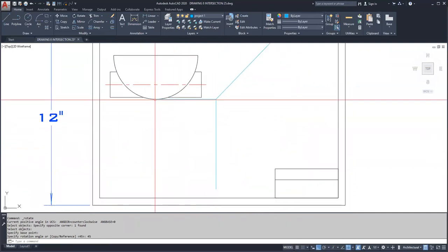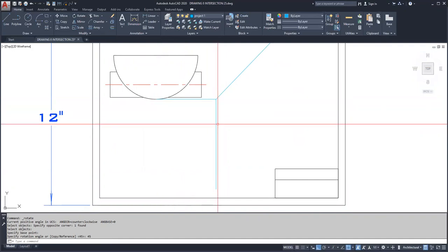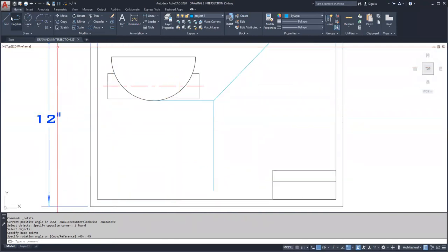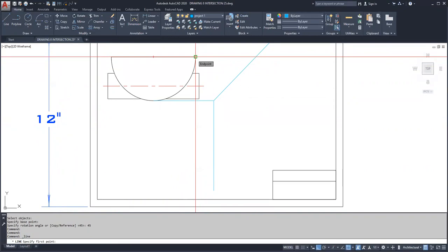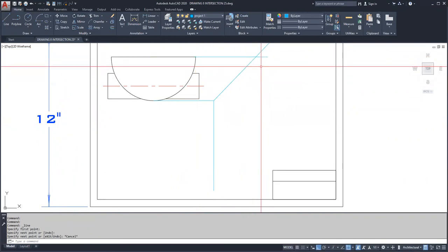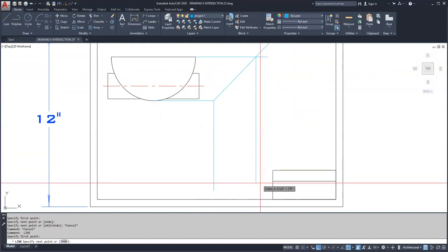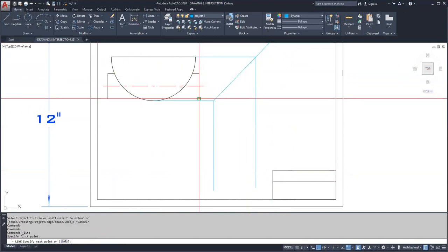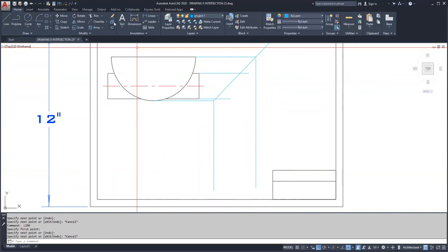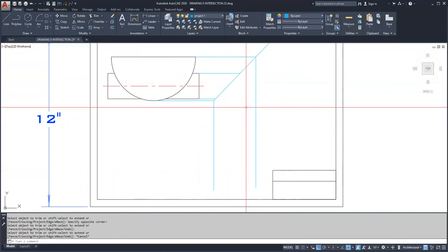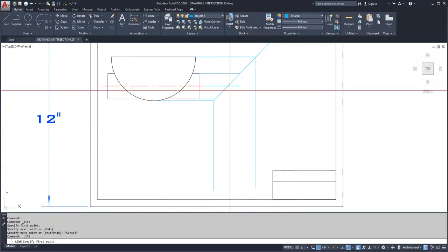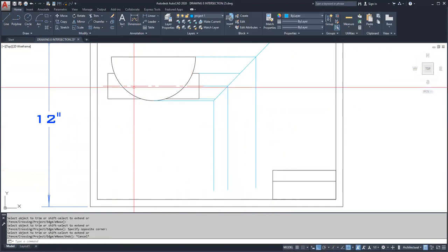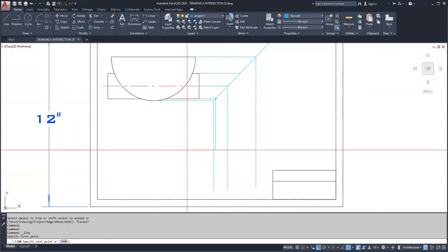So again, you go from the lowest point of the object, and then basically you can create the point going down wherever you like, and at that intersection is a 45-degree line. So come from the highest point here. When I hit the 45 line, I can drop down straight. And let me just clean that up fast. And also from the cylinder, right here and here. You can actually also project the center line if that helps you. And there's the center line. Drop these all down from the 45-degree line,